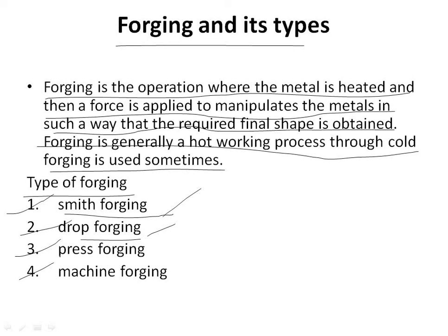Next we will be discussing press forging. Press forging is similar to drop forging. It is also done in closed impression dies, with the exception that the force is a continuous squeezing type, applied by a hydraulic press.